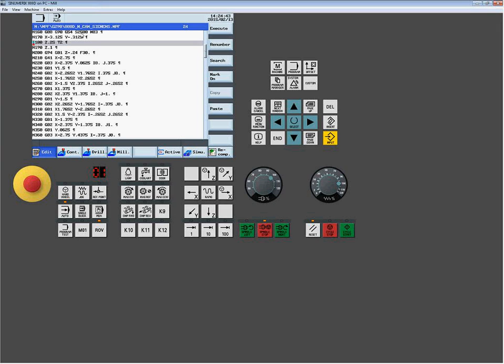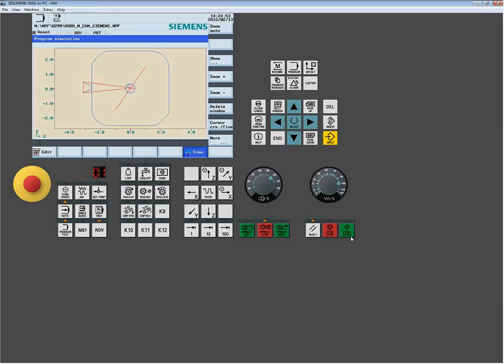This actual machine isn't designed for prefetching. Watch what happens when I simply just delete this instruction that's not needed. Now if we go to simulation and we rerun this part, now we see a completely different cutter path. It's important to start to understand how these commands build and understand that depending on the technology of the machine I'm on, they may function very differently.